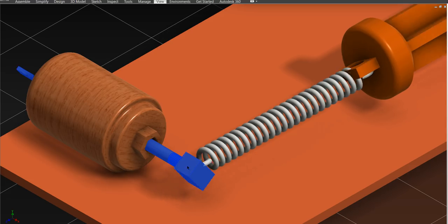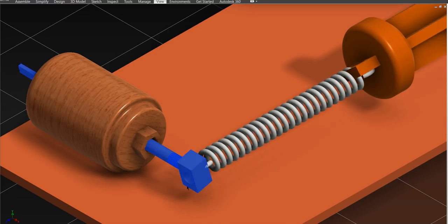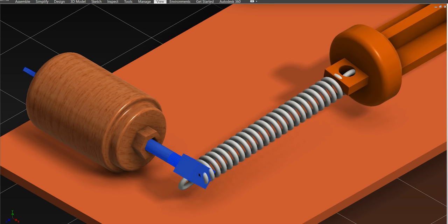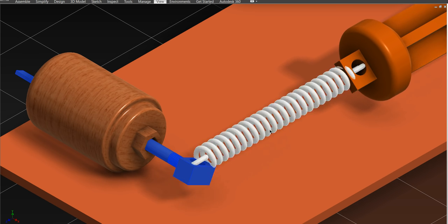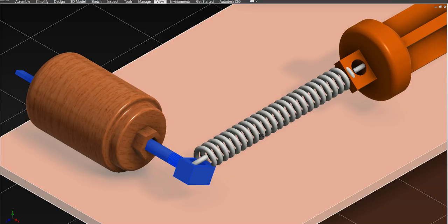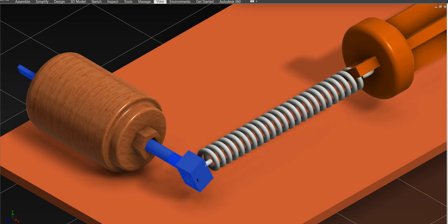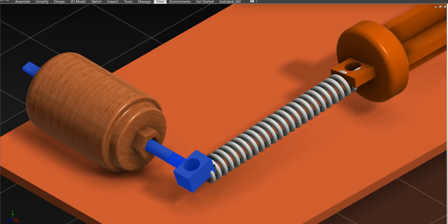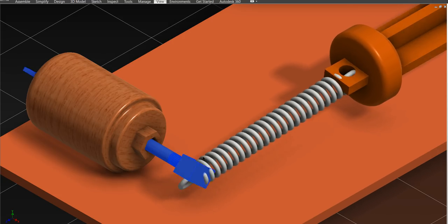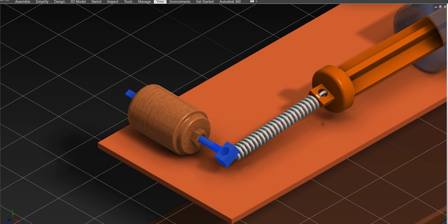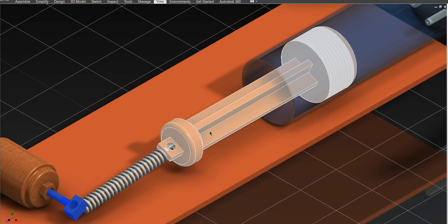This shaft gets rotated when there is electrical energy supplied to the motor. When this gets rotated, there is an extension spring that actually gets a torque due to the shaft, and when this gets a torque, it in turn provides some kind of force to the piston of this cylinder.